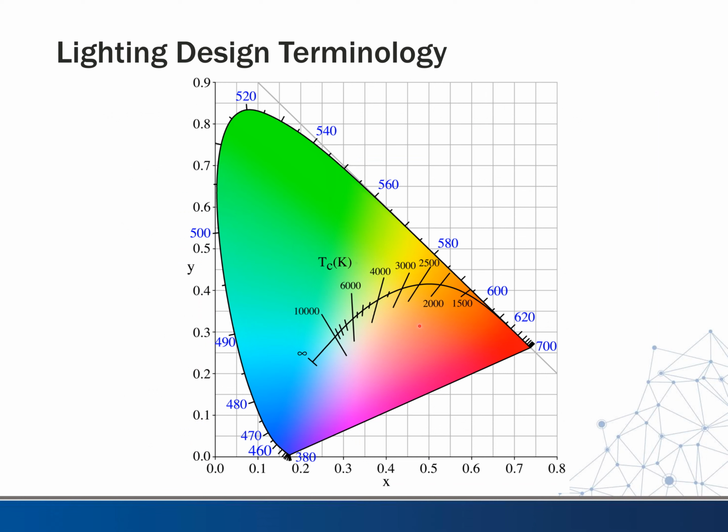I wanted to take a quick look at the chromaticity chart that we mentioned. So this is the chromaticity chart. And this is the original color temperature range here, going from red to the bluish region. When we had a filament, this is all we had. But then we realized as we started getting different types of bulbs, all the way up to, and especially LEDs, we could get colors off this line, so we could get them anywhere in this region. So that's why we went from the color temperature linear range to the chromaticity two-dimensional range. This is why you can get an XY coordinate to describe the color of a light bulb.